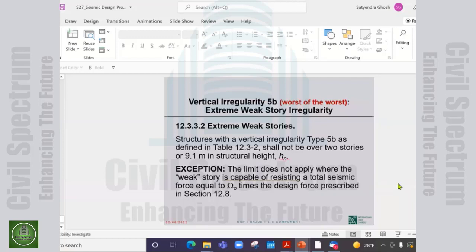Okay. If you use a rationally computed period, you are assuming a softer building, a building with less stiffness. If you ignore the limit of C sub u T sub a, you are further decreasing the stiffness of your building. If you decrease stiffness, you'll be calculating larger drifts, and the code has no problem with it. You are shooting yourself in the foot.